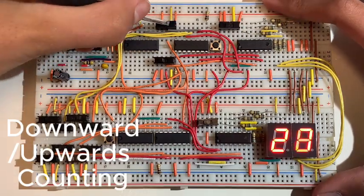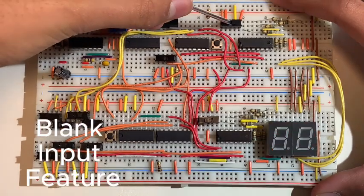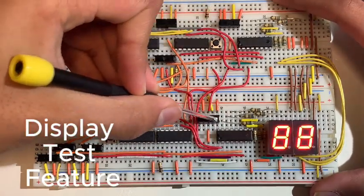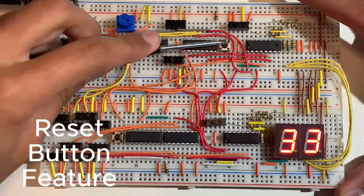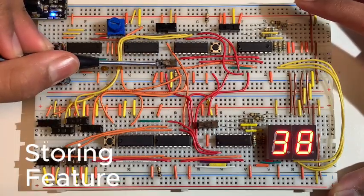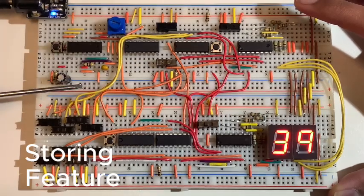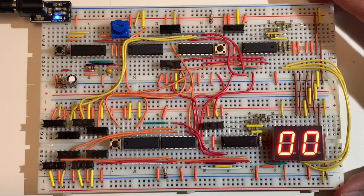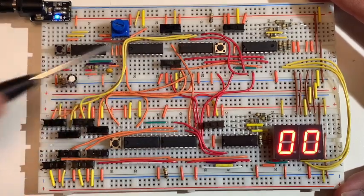Instead of adding a second button for each feature, the original button or switch is wired to the corresponding pin on the second set of chips. For example, the store switch is connected to the pin on both 4511s, so both digits are stored simultaneously when toggled. As mentioned earlier, a preset function is built using the 4510 ICs.